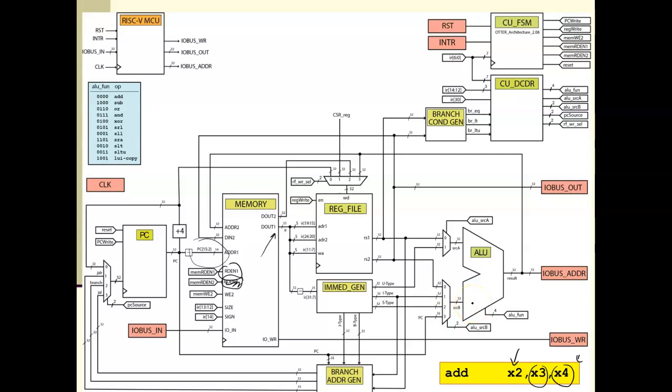So check it out. We know we're getting these values out of the register file, and so the very first thing we have to do here is get this data into the ALU, which means we've got to turn this mux on. So we'll say this mux is equal to 0, because that allows that path of data into the top part of the ALU. Now the notion here is that it could be 0 or 1. If I choose 1, it chooses this input there, and that's not what we want. We want to add the contents of 2 registers. One of them is RS1, the other one is RS2. So this source B here is going to equal 0, 0. And so that gets us the data into the ALU.